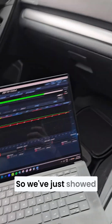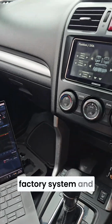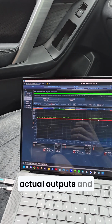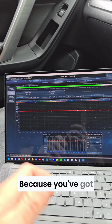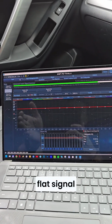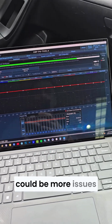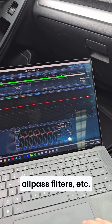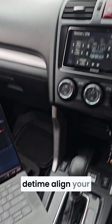So we've just shown you how to effectively de-time align your factory system, and then you can start moving on to your actual outputs and do your actual output EQ tuning, because you've got flat signal from both of the left and right channels. Obviously there could be more issues like filters, all pass filters, etc., phase issues, but for the time align, this is how you de-time align your factory system.